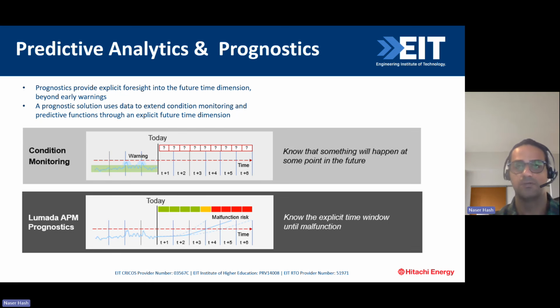Condition monitoring is required because we can understand the condition of the equipment at this stage. But I also need to know how much would be the probability of failure for the equipment in the next 6 months, 1 year, and what would be the percentage if the failure mode, for example, is going to increase to 50%.